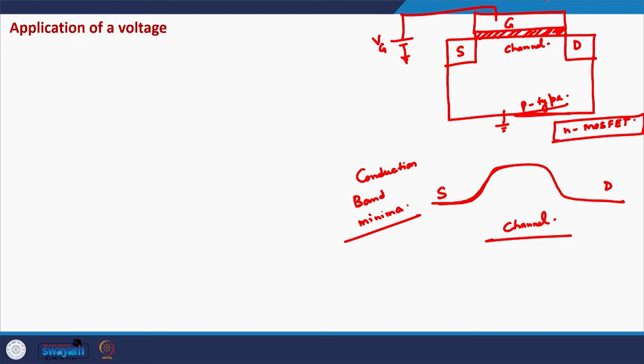So in this direction, the MOSFET works as a capacitor in a way, because we have a metallic plate, the gate terminal, on one side, in between we have an oxide, and on the other side we have a semiconductor material which can have charge carriers. So this will behave like a capacitor.